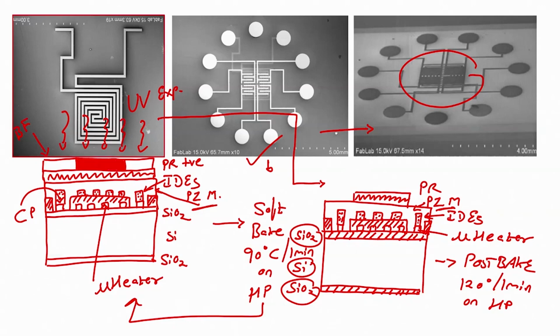We only want piezoresistive material on these electrodes, we do not want it on any other side of the chip, correct. That is why we have used photoresist, and patterned it so that it protects the piezoresistive material below it only in the wanted area. If I put this chip in a piezoresistive etchant, whatever material we are using, what will happen?